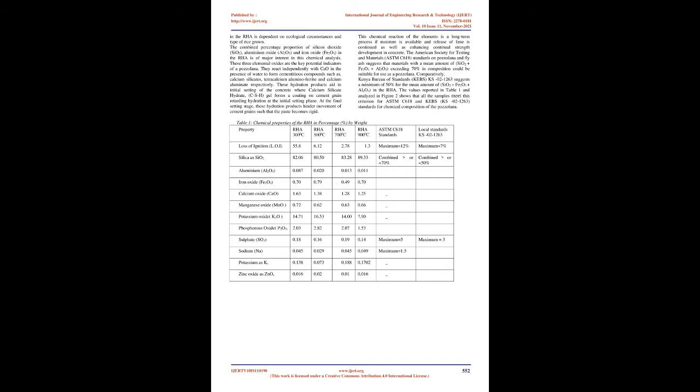At lower temperatures of 300°C, the ashes were observed to be black, and then turned into white-gray, white and pink-white at higher burning temperature. The difference in color transition is due to the removal of unburnt carbon content in the rice husks ash. As the temperature increases, residual carbon content decreases. At these temperature ranges, there is a complete reaction of sequence from amorphous silica to crystalline silica, cristobalite and quartz. To eliminate significant amount of unburnt carbon from the ashes, burning should be done to higher temperature of at least 500°C with significant amount of burning time. Color is an indicator of the amount of carbon content present in the ash.